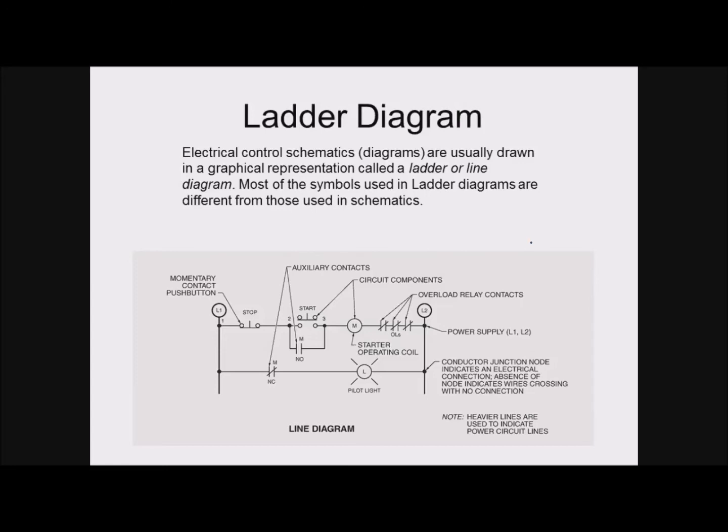So we have special devices that actually sense overcurrent over time, and these are called overloads. These overloads look at the current going to the motor, and if it pulls too much current over a certain amount of time, then it'll trip the motor out, and we call those overloads.